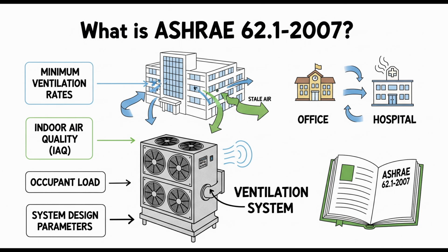In that case, your Ez might be lower, maybe 0.8. And if Ez is lower? It means you actually need to supply more total outdoor air into the zone, Voz equals Vbz over Ez, to make sure the breathing zone still gets the target amount, Vbz. You have to compensate for the less effective delivery. Okay, so Ez is about getting the air to the people within the room.